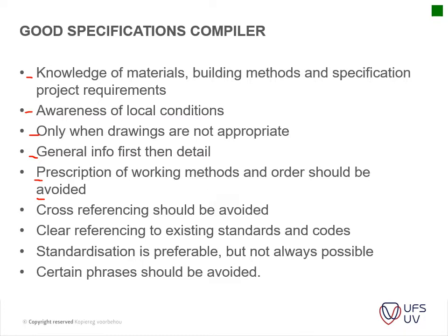Cross-referencing should be avoided, and especially in our computer age, it's a thing that crops up quite often. Whenever you're duplicating certain sections in a drawing, it does pop up quite a lot, where you maybe forget a construction line, or the lines have a different font setting, etc. Especially if you're working from old drawings to new drawings and the line settings aren't exactly the same. I've encountered that quite a bit.